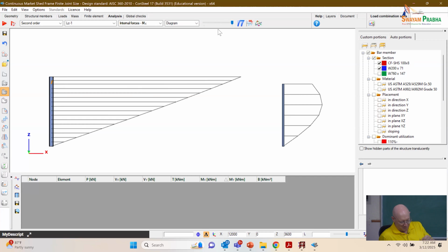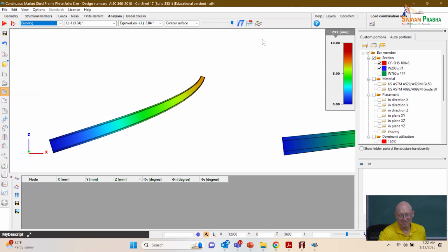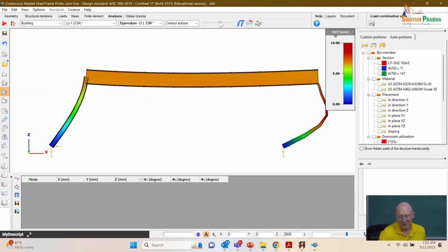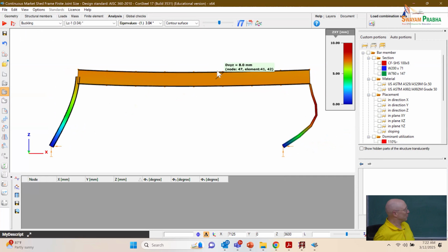So this is what I was mentioning yesterday when I said, sometimes you can add material or you can add continuity and you can make a structure weaker. So let's look at what we've got for the buckling load on this. We'll go back to the full frame, and tone down the exaggerated displacement a bit. So it's buckling like so. Remember, the buckling load we had with the previous model was 3.74. This is now gamma critical equal to, what, 3.04?